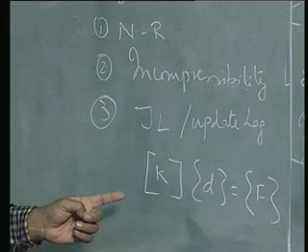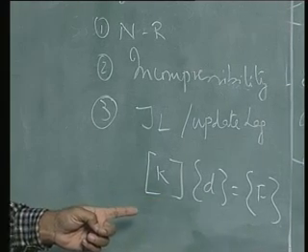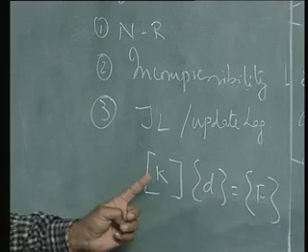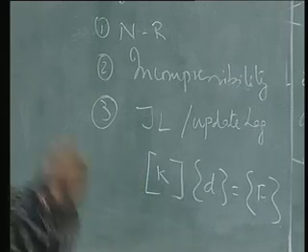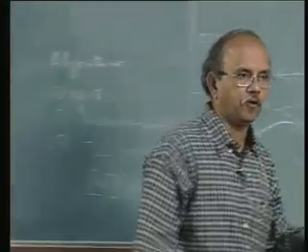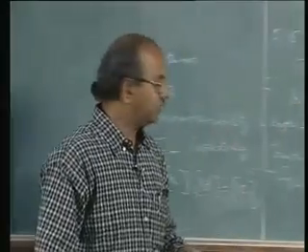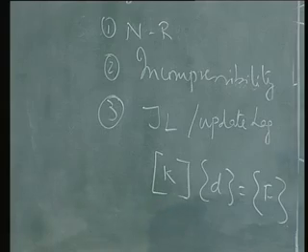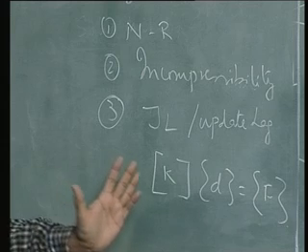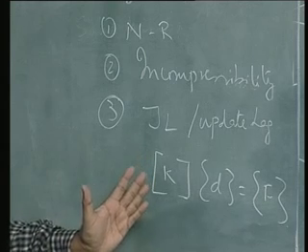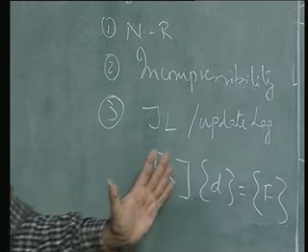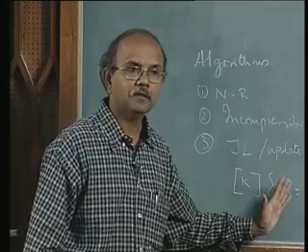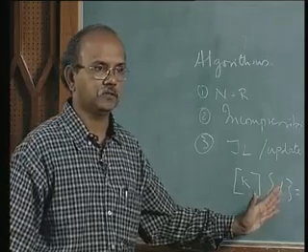Okay, this is the fundamental equation we solve, and when we solve that, all of us know from our earlier fundamental finite element course that determination of K is one of the major issues in the element formulation, and that we see that this K is independent of the, what is the assumption that we make ultimately when we get this formulation? K is independent of the D that goes in.